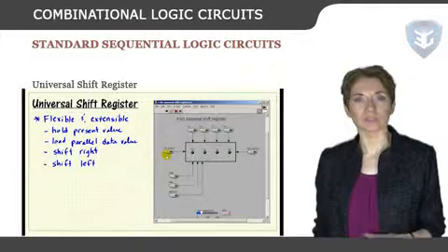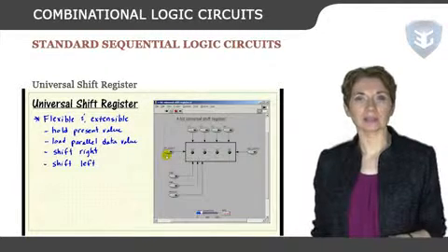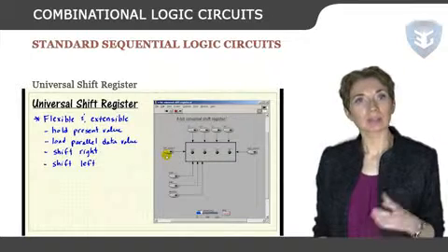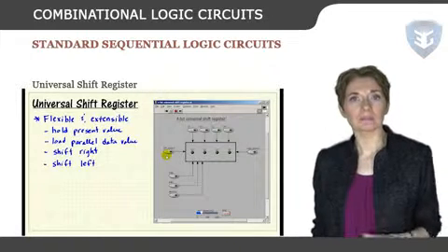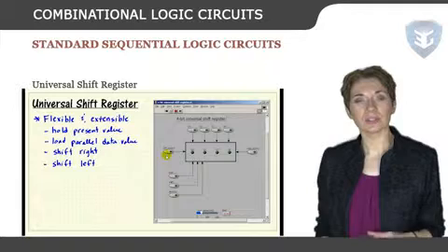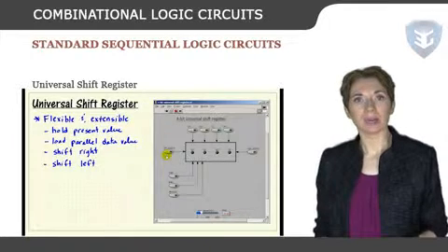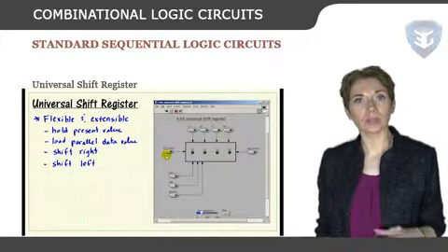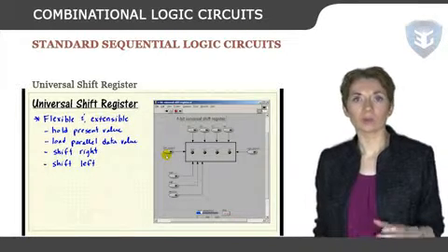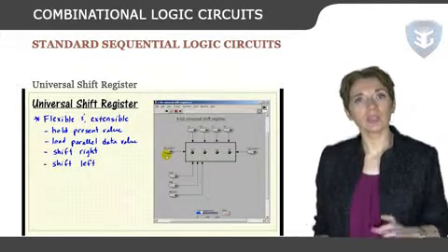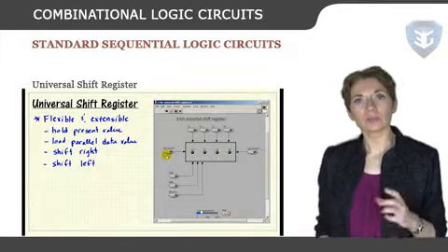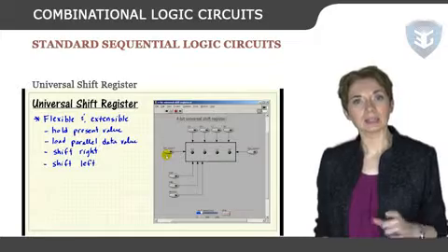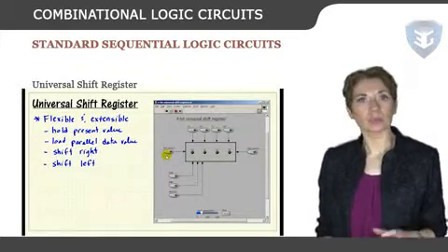Universal shift registers are very useful digital devices. They can be configured to respond to operations that require some form of temporary memory, delay information such as the SISO or PIPO configuration modes, or transfer data from one point to another in either a serial or parallel format. Universal shift registers are frequently used in arithmetic operations to shift data to the left or right for multiplication or division.